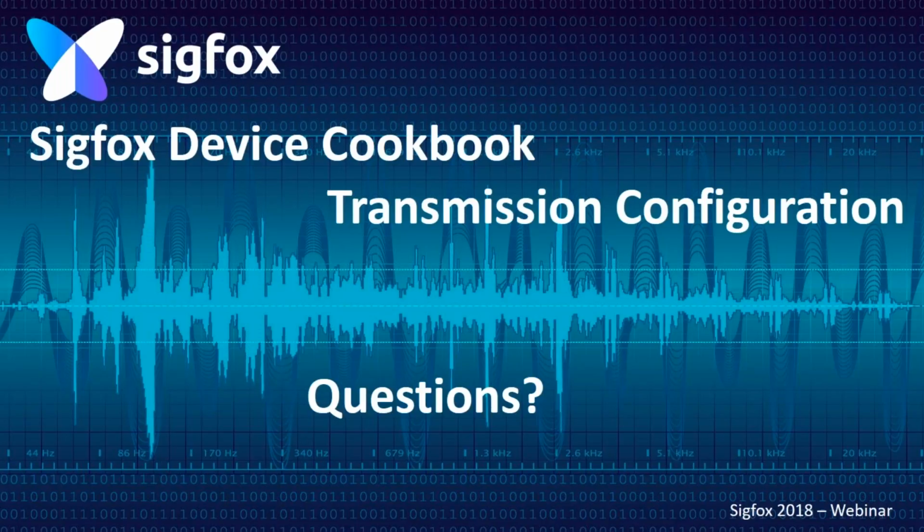But this is not satisfactory from an engineering perspective because you can do much better. What is extremely important is managing the standby current and the sleep modes of your internal systems. And every damn 100 nanoamps will cost you days and weeks of autonomy.